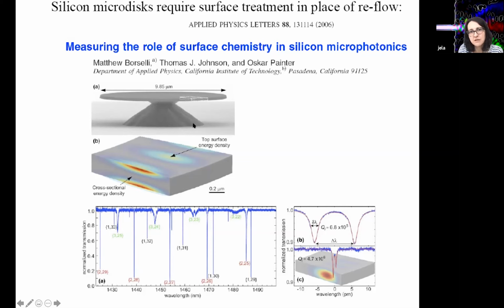And keep in mind that this pedestal has a refractive index that is much higher than the refractive index of air. So you will basically have your field leak through the pedestal, and that is affecting the Q factor. So it's a combination of effects. I agree there is also the effect of coupling to the fiber, but the most dominant effect here would be the pedestal, which is why you'll see a dramatic change in the Q factors of modes with lower n and larger n.